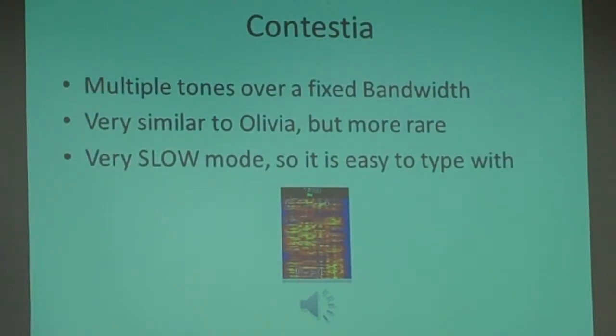But the biggest problem you see is people running their preprocessor up. You need a little tiny bit of it to run the digital modes, because the audio is coming into the mic input. So the preprocessor should be there, but compression should be off, and you shouldn't run the preprocessing very high.